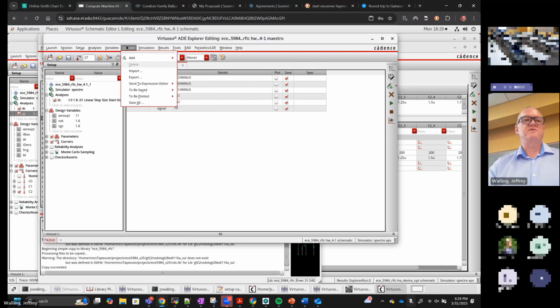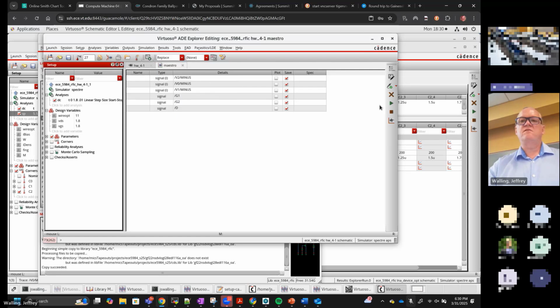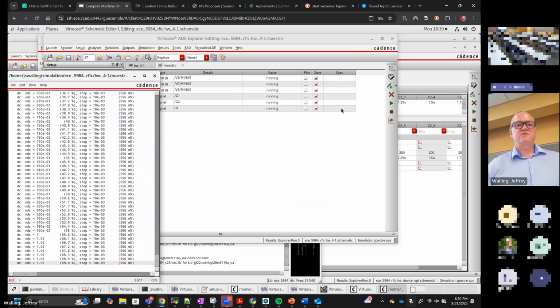I like to add some equations to the mix. One of the things that is going to become important for our switching amplifier, for our Class A amplifier, is that we need to go through the full range of voltage and current. But we have a cascoded transistor, so the full range of voltage is going to include some effect from the knee voltage.